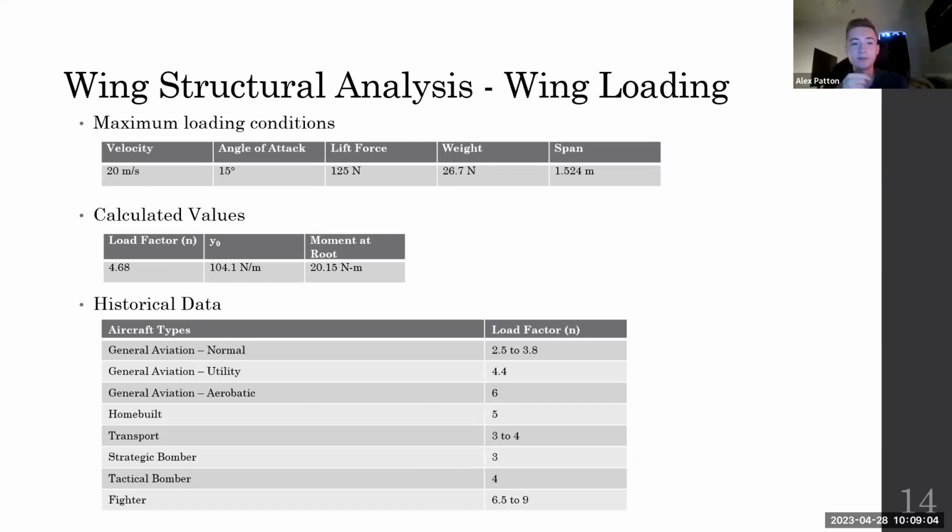We did not, because it'd be really hard to calculate a crash condition. So we just kind of hope for the best using our carbon fiber spar. And again, we had that safety factor of a little over 3. So we thought it would be fine for that. Okay. And does this assume an infinitely stiff fuselage? I'm sorry, what was that? Does this assume an infinitely stiff fuselage? In most cases, your wing is probably going to be stronger than your fuselage. Correct. It did assume that.